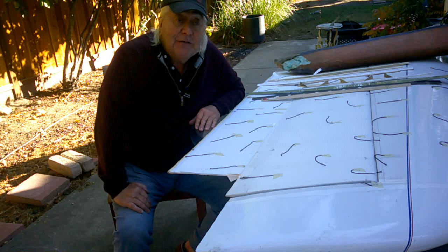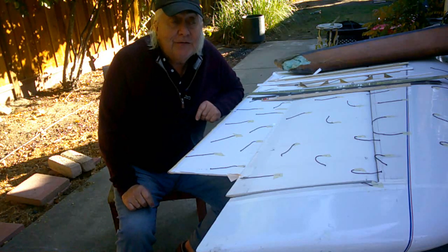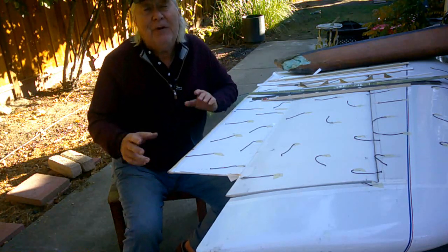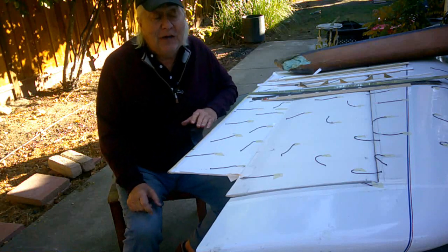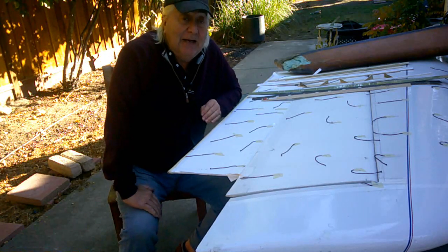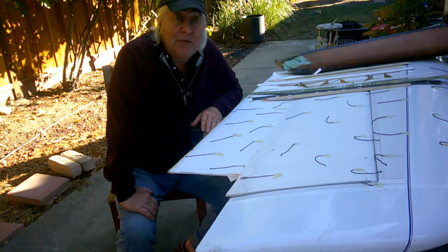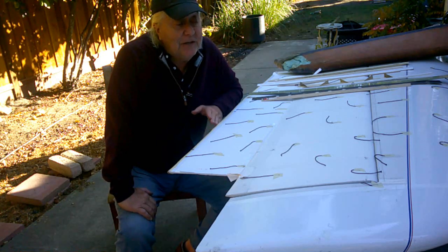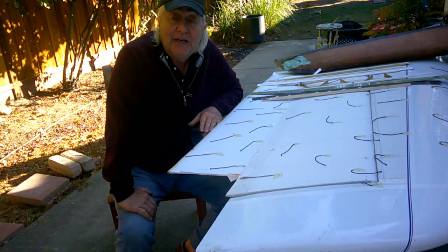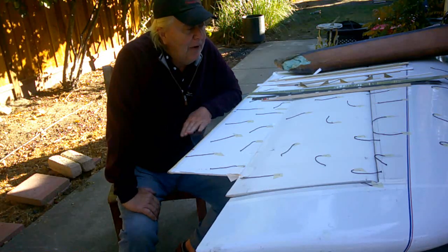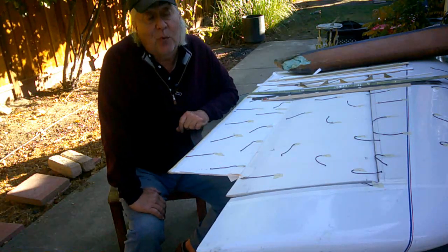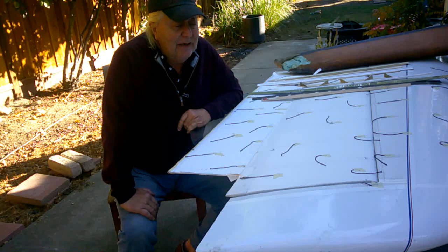Okay, so one way to cure problems is to avoid them. You don't really fix the problem, you just don't cause it to happen. And we went through a bunch of stuff, we figured, at this point, the best thing I can do is just don't deflect the elevon more than 15 degrees. So I actually set up some differential in the elevons, and I wanted to give myself a little bit of margin, so I said, okay, I'll take it to 20 degrees, and that'll be enough.